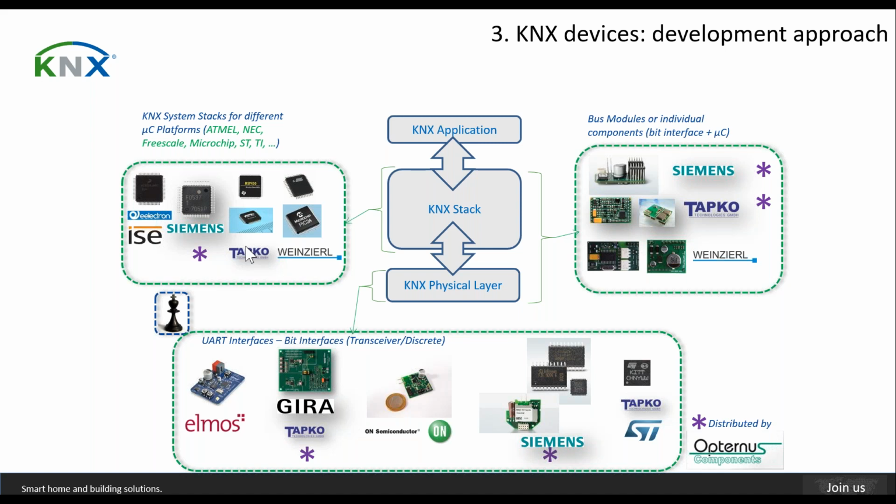You can see options just for physical layers, options for licensing KNX stacks, or bus modules or individual components that give you physical layer and part of the KNX stack or a full KNX stack. But in this case, unless you go OEM with an existing product, you need to develop your application program. So this is the actual functionality of the product using the manufacturer tool.